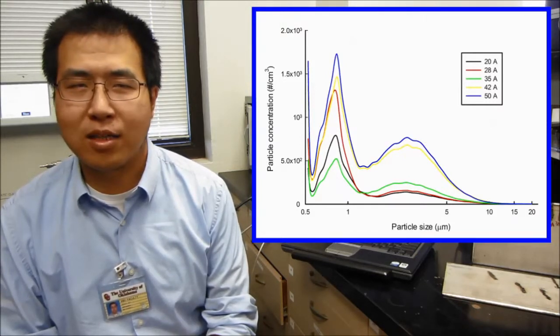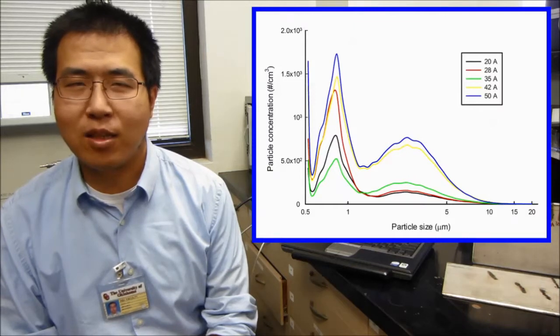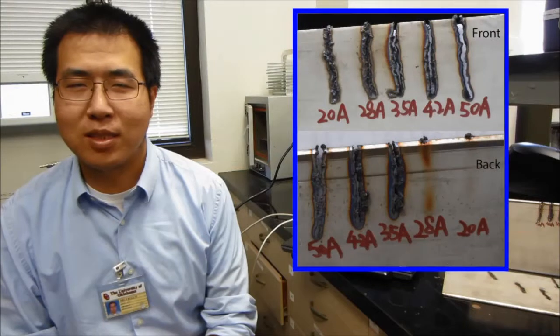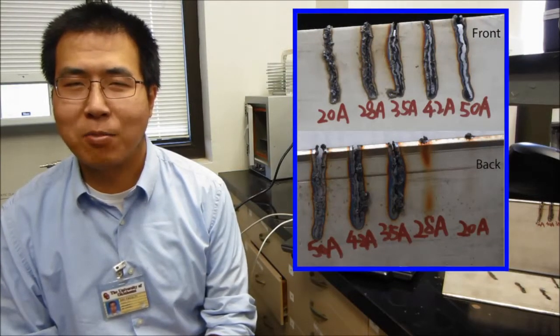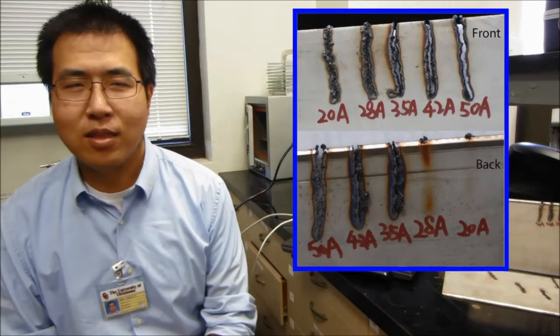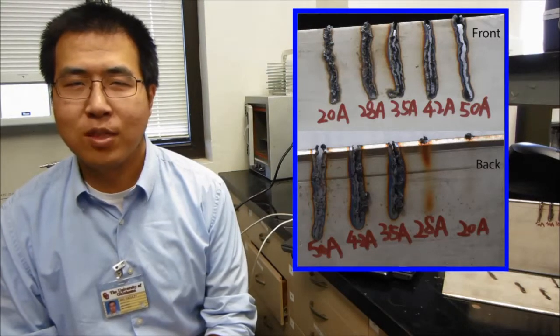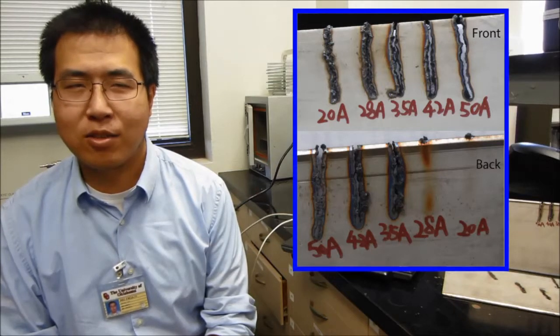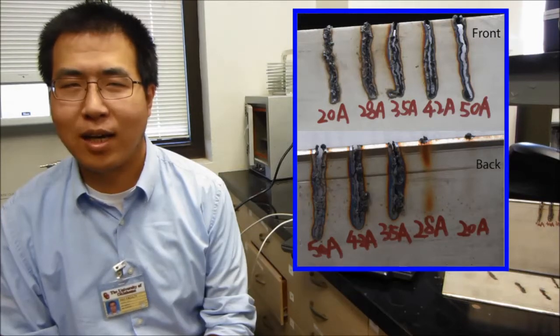Exceptions were at the median arc current, 35 amps. It gives the lowest total count of particles. The low arc current cutting doesn't penetrate the 3/16-inch stainless steel plates, while the highest arc current gives a wide and deep cut. So at the low arc currents, a hot metal pool was formed in the arc zone, vaporizing metals, while at the high arc currents, the high temperature also melted a significant amount of metals while moving along the cutting lines. So the median arc current gives a cut that is done but with a lower temperature, so the vaporization of metals is at a minimum, thus producing a low count of particles.